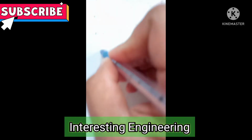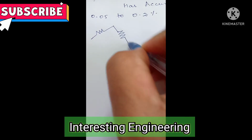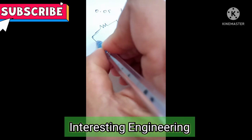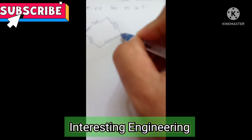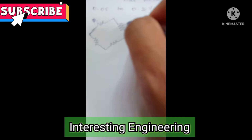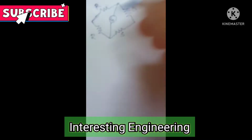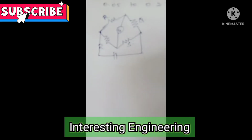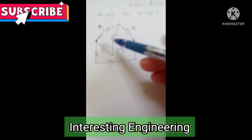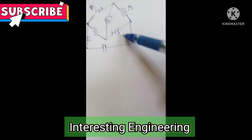In the Wheatstone bridge circuit, we have 4 resistances connected in a bridge arrangement. 2 arms have fixed resistances. This is the P resistance, Q resistance, R is the unknown resistance, and S is the standard resistance, and in between we have a galvanometer, and to this entire bridge arrangement we connect a voltage source. So this is the normal Wheatstone bridge circuit where we have 4 resistances P, Q, R and S, where R is the unknown resistance and S is the standard variable resistance.